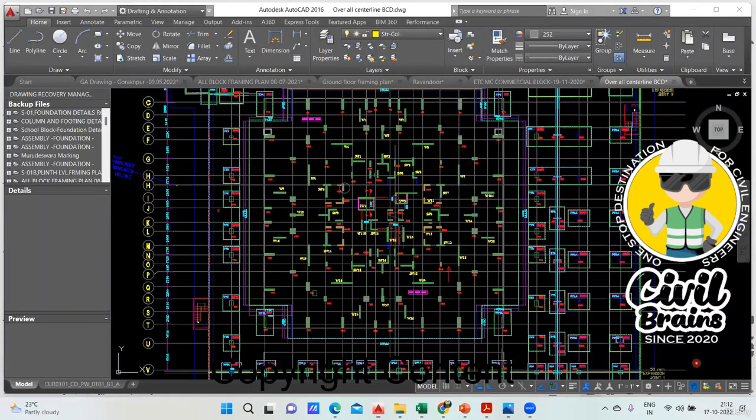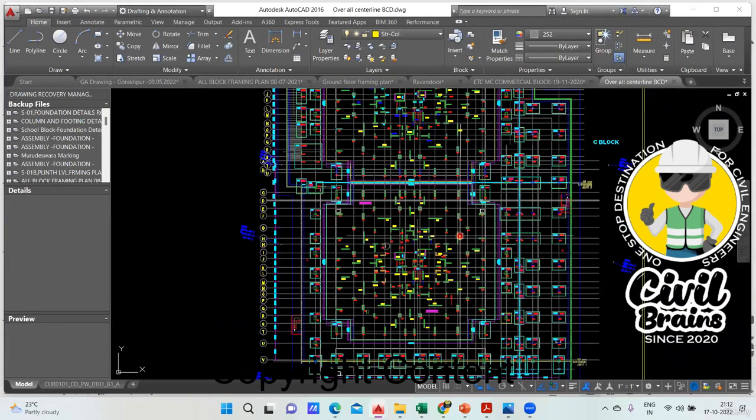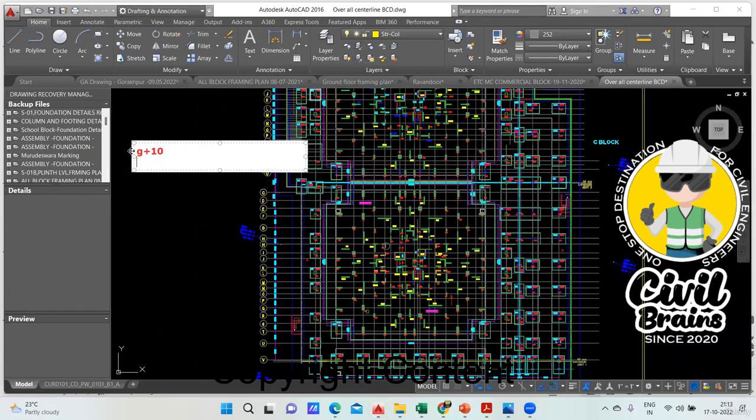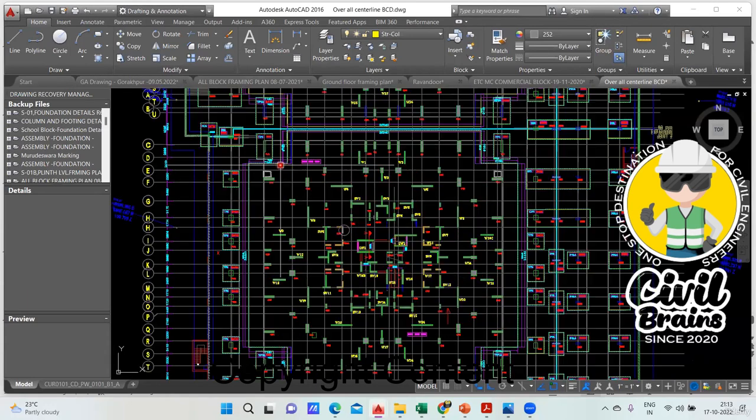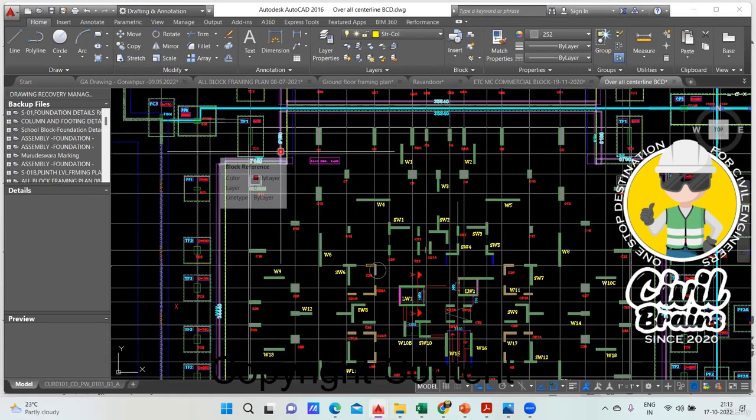You can see here it's a huge foundation, and usually we use a raft foundation when you have a huge building. For example, if you're constructing a ground plus 10-story building, or let us say a ground plus 8-story building, and it depends on soil conditions also. But typically up to a G plus 5 building we don't use a raft foundation. We usually go with normal isolated footing or combined footing, which is sufficient. But when you go for a very high-rise building or big commercial buildings, the best practice is to go with the raft foundation. But again, it depends on your soil conditions.